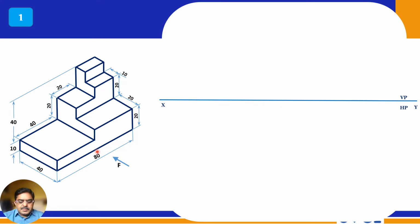So this is 80 mm width we have. So draw an 80 mm line, and then this 20 mm is visible, right? 20 plus 20, and this distance is 50 mm. Total distance is 50, so 50 minus 40, and this height will be 10 mm, right? So 20, 20, 10, 50 mm. Draw a straight line, and then this edge is visible, and this width is nothing but 40 plus 20, 60. 80 minus 60, so this length will be 20 mm.